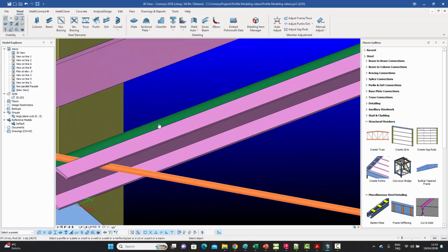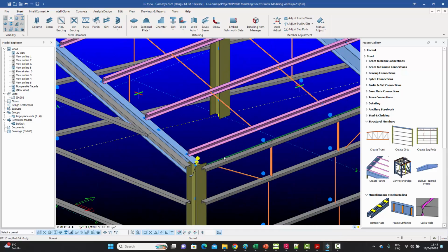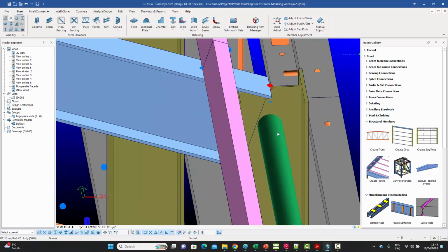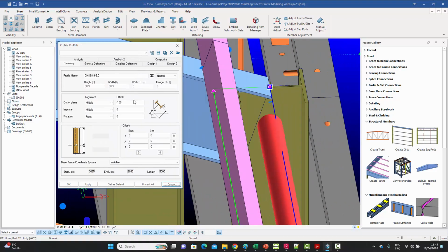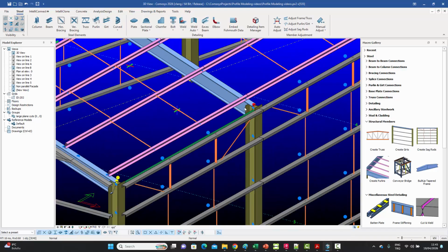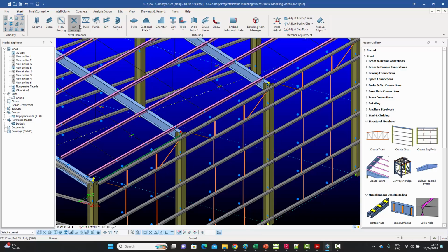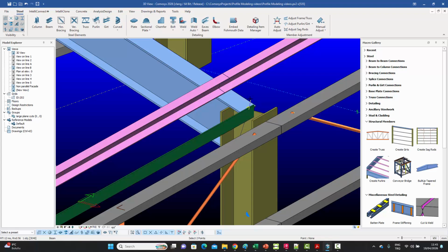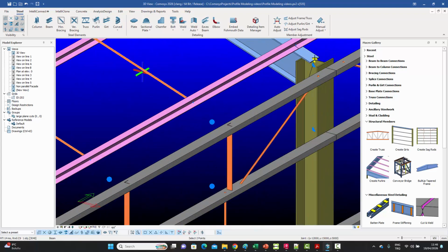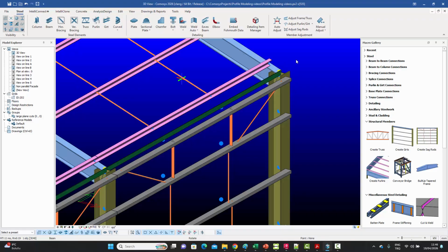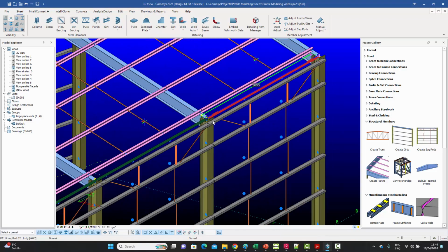I think we just created one over here. That was the one, and it was lowered by 150 as well. There we go. So we want this offset of 150 in this one as well, because the height of the roof beam is 150, so the middle will be somewhere over there, and we've lowered that, and then we can continue like that, over there. Always make sure you're connecting to the right point.